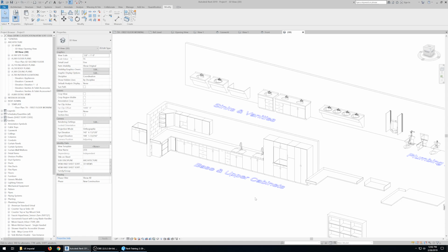And then in your project environment, you have to load that same shared parameter so that your schedule can recognize, hey, that family is telling the schedule that this is a 3070 single door, and this is a 3070 pair of doors. Big difference. Contractor needs to know, because he's ordering obviously two doors instead of one, and door hardware and stuff like that. So we'll get into shared parameters when we get into the next environment as well.